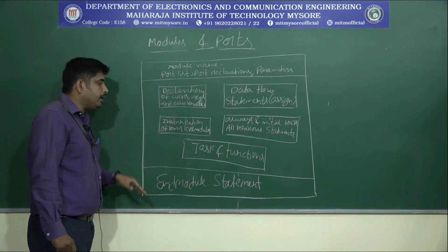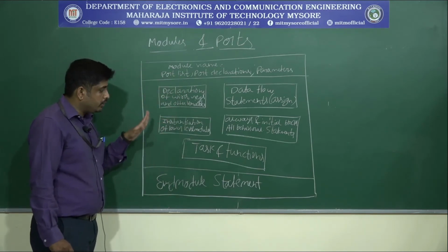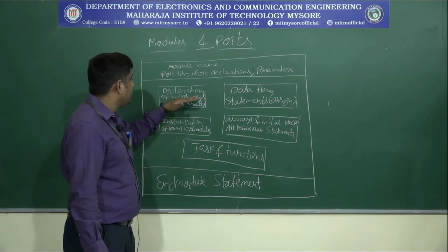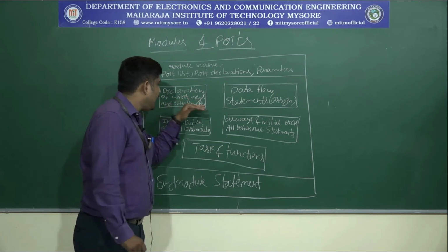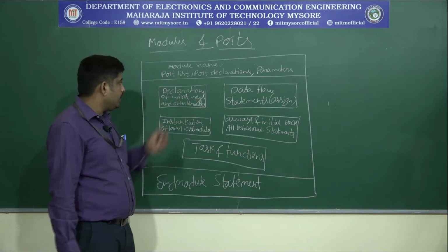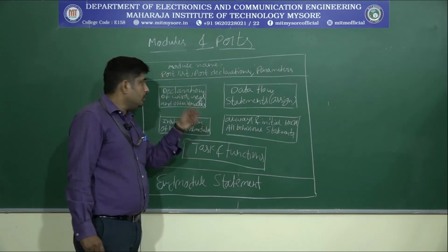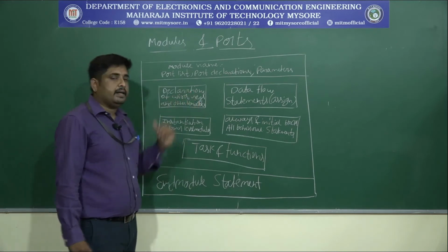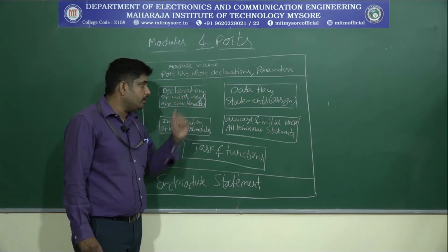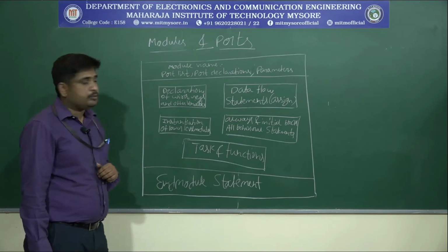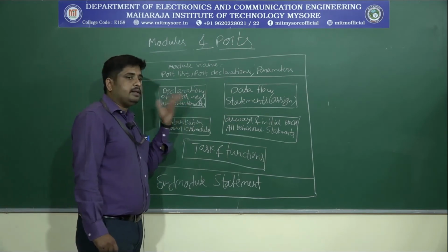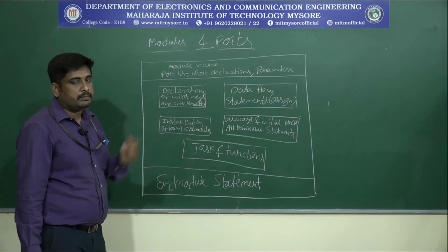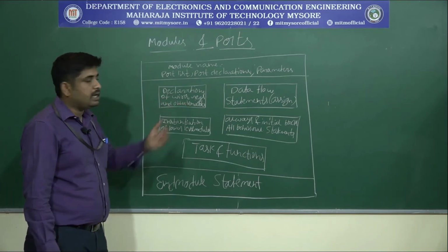The second part is where you mention the logic. It is divided into 5 parts. In the first part, declaration of wires, registers and other variables. Here you mention things other than inputs. Other than inputs means wires, which we call intermediate signals. Then registers, which are specially used in behavioral description. Then if you want other variables, sometimes real variables or decimal numbers, you have to mention them.